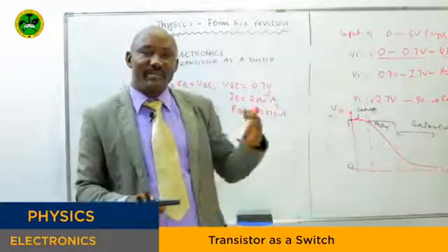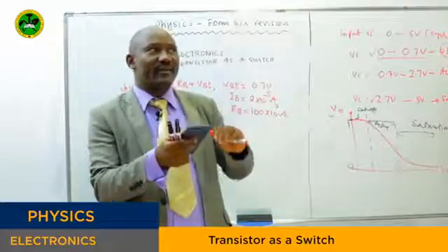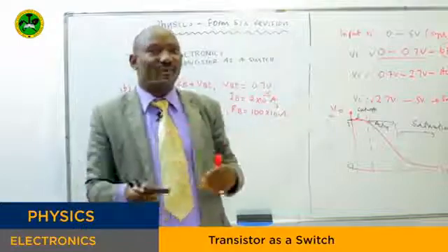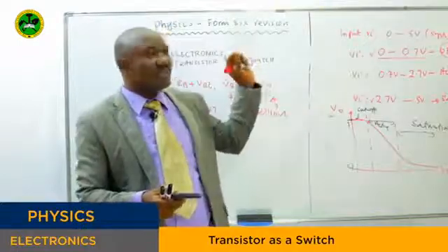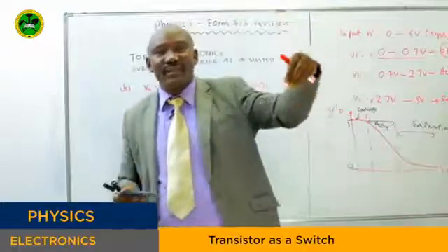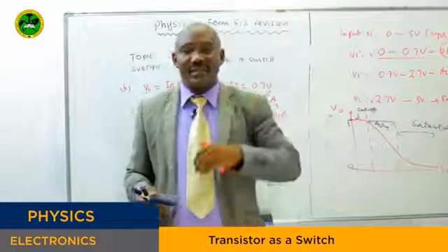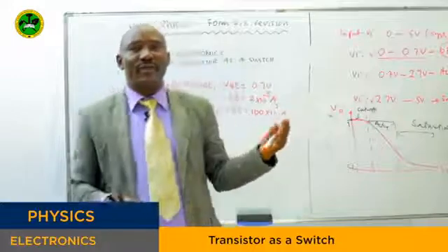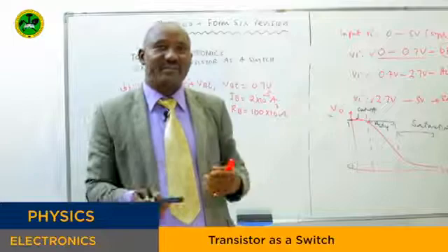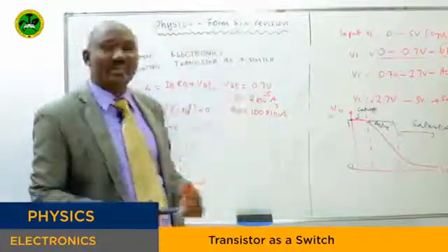This is through the capacitor and the resistor, and we remember we have different types of multivibrators. We did this in your class. We mentioned some areas where you can use that. When you have two transistors whose saturation points differ slightly, we can have them connected such that the output of one transistor feeds the input of the other. This is what forms a multivibrator, and we mentioned the types: mono, bi, and astable multivibrators. These show how a transistor can be used as a switch in various ways.